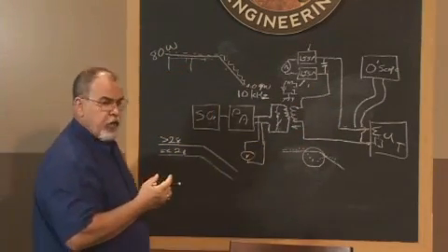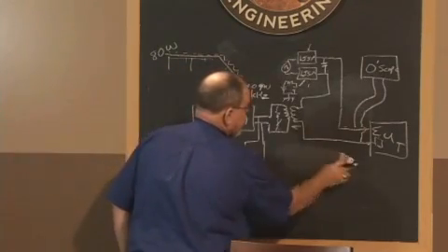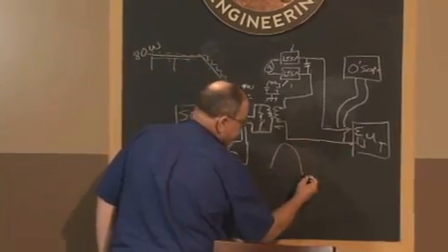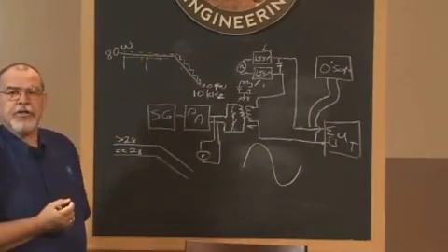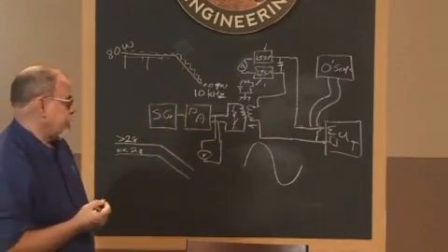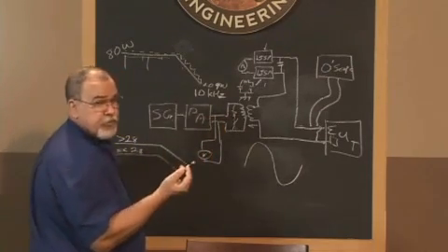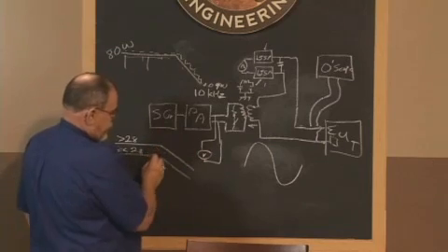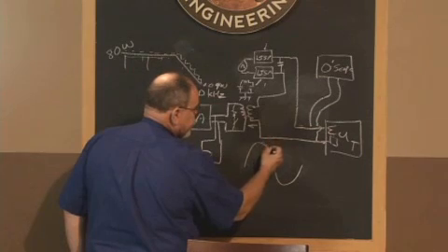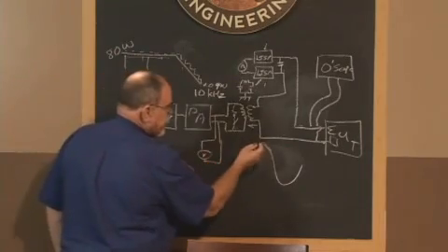Now, here's an inherent problem. I've got a very big signal, okay? Because our test article happens to be 115 volts. So now I've got this 115 volt 60 hertz signal that is present on my oscilloscope. I could get to see that, okay? Now I'm trying to apply a very low level, 3 volts, 4 volts, some very low level signal in my test limit on this. So what I see is a very small excursion happening on that 60 hertz. That's the part I need to measure.